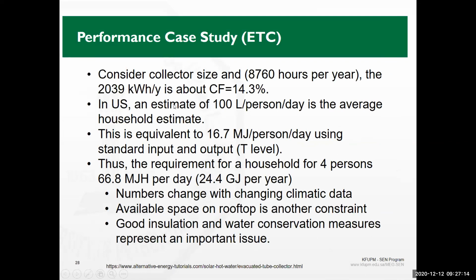If we are talking about sizing of solar collectors in a place or in a house that has 4 persons or n number of persons, then the standard rate is 100 liters per person per day. So if we are going to come up with a solar collector system, then your values should be around this. How many persons are there? And then you can estimate the total heat of water that is to be heated per day. It depends on the number of persons accordingly.